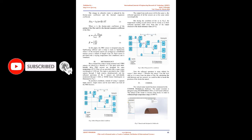FBG sensor. An FBG is a short segment of optical fiber that reflects a particular wavelength of light and transmits all other wavelengths. It acts as an optical notch filter. The reflection is due to the grating patterns inside the fiber. FBGs are built by using holographic interference or a phase mask to expose a small length of fiber to a periodic distribution of light intensity. The wavelength is reflected based on the Bragg's equation.